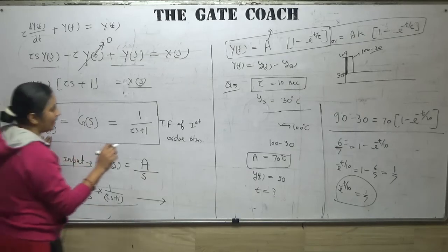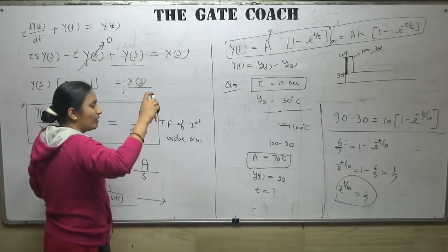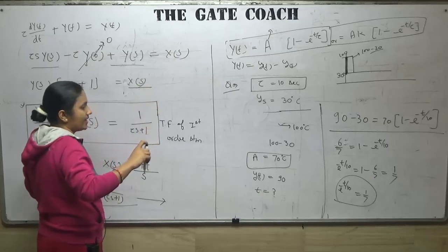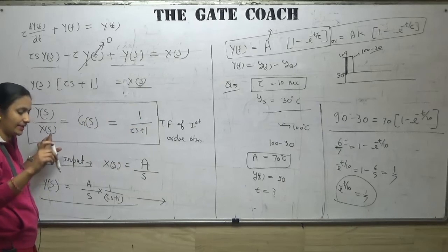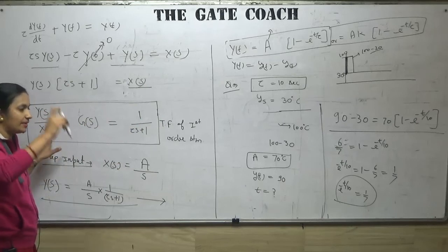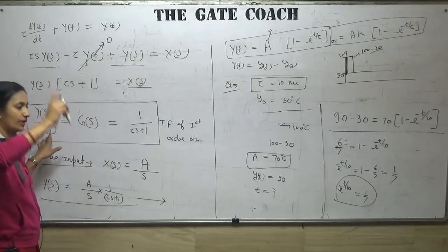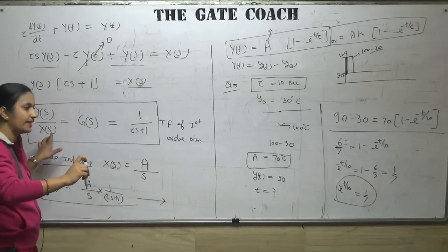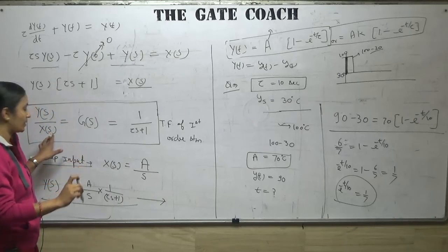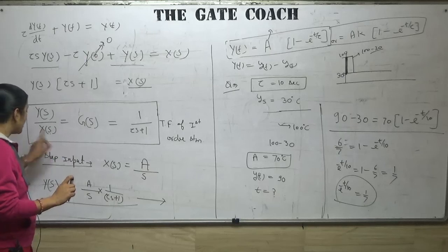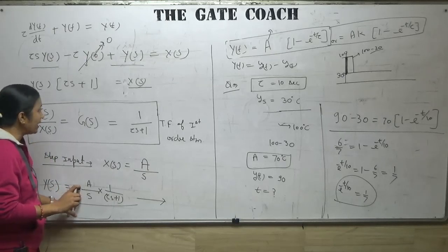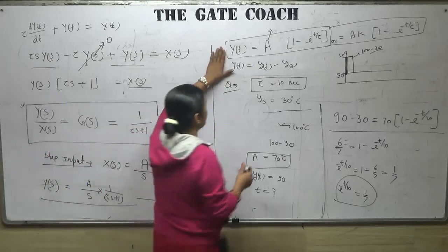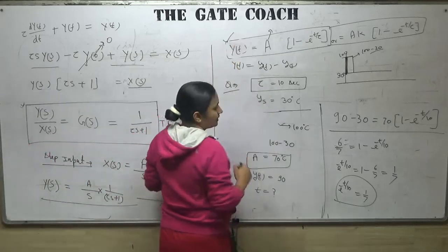They are saying that we have put the thermometer in 100 degrees centigrade. They are not saying they have dipped it and picked it out. They have said we have put it in 100 degrees centigrade, which means it's an example of step input. So we substitute the value of the step input into your first order system, and that gives your response equation, y(t) for the step input.